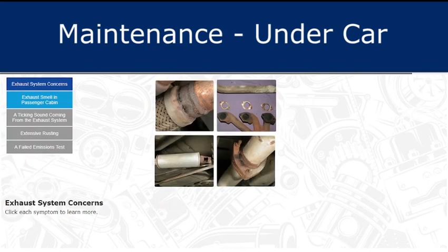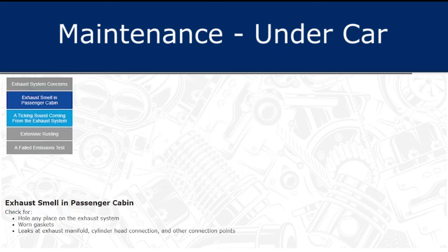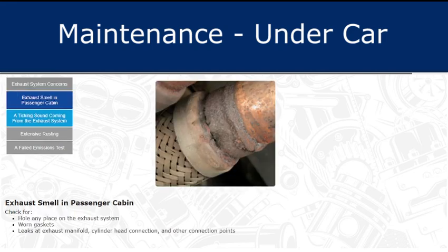Several symptoms are related to exhaust system concerns. Select each button to learn more. When finished, select Next to continue. The smell of exhaust in the vehicle signifies a leak. Watch for leaks at the exhaust manifold, cylinder head connection, and other connection points.